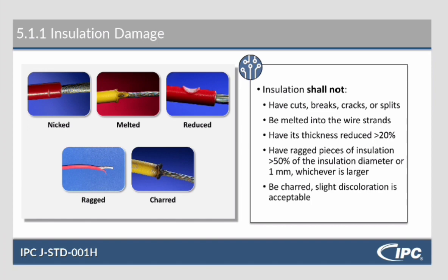Slight discoloration is acceptable. That happens sometimes when you're using thermal tools like soldering irons, thermal strippers, or heat guns. A slight discoloration that could come off is acceptable. Something like this, though, that is just straight up burnt, is not going to be acceptable.